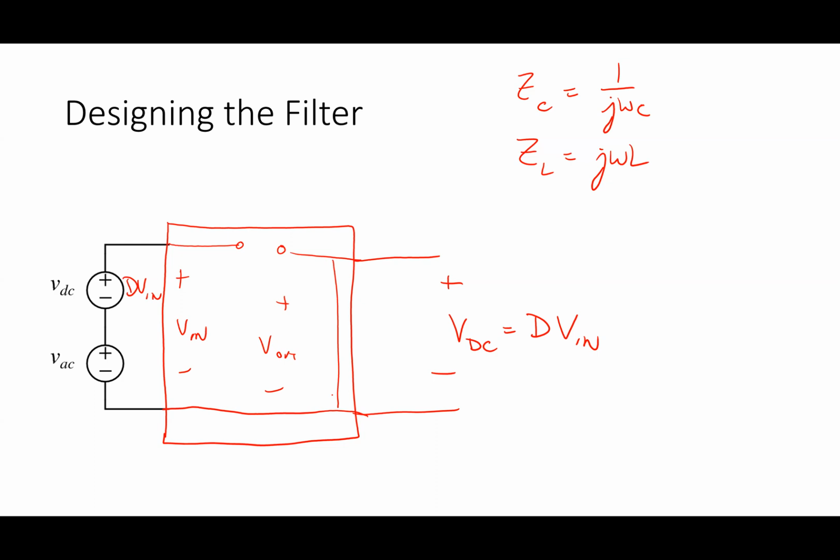Low frequencies can make it through. Now the question is, what's high and what's low? That's usually the key point, and that's where the design of a low pass filter fits in. What would be the frequency that matters, do you think, for this guy? You could do the transfer function and find out the corner frequency, but roughly, if you had to guess without doing the transfer function, what would it be? Roughly 1 over square root LC on the omega side.